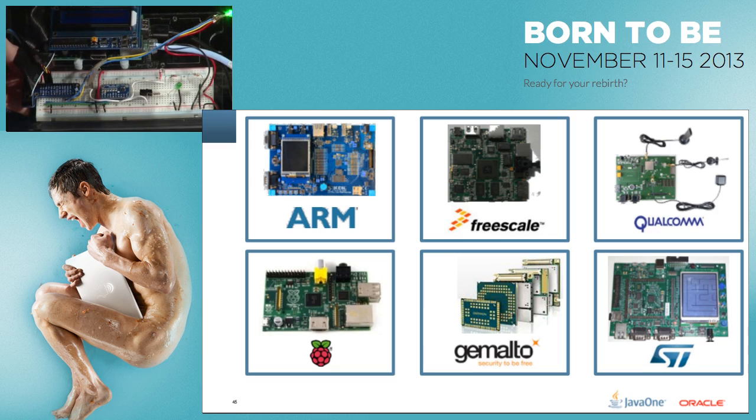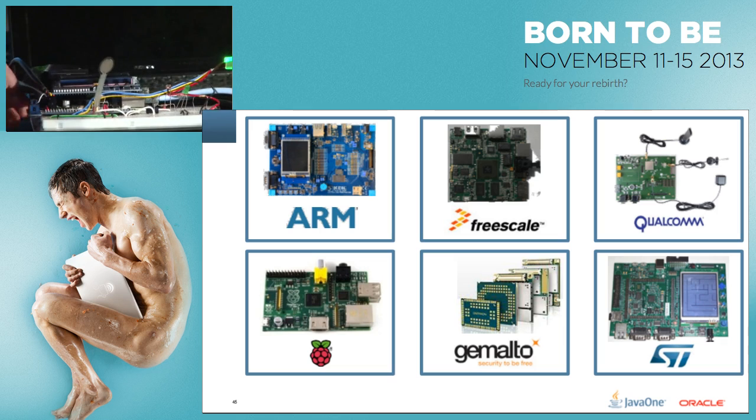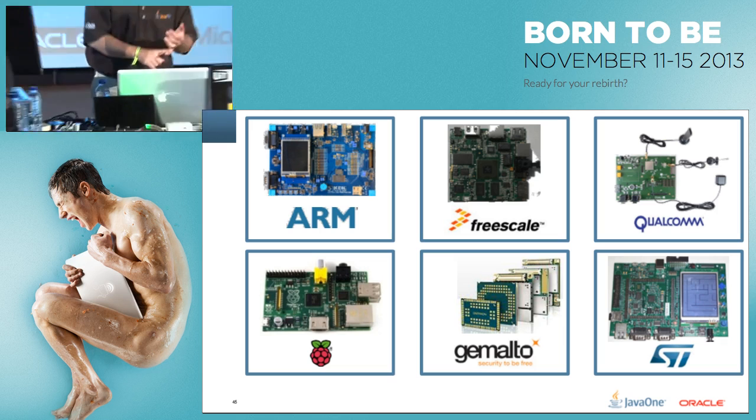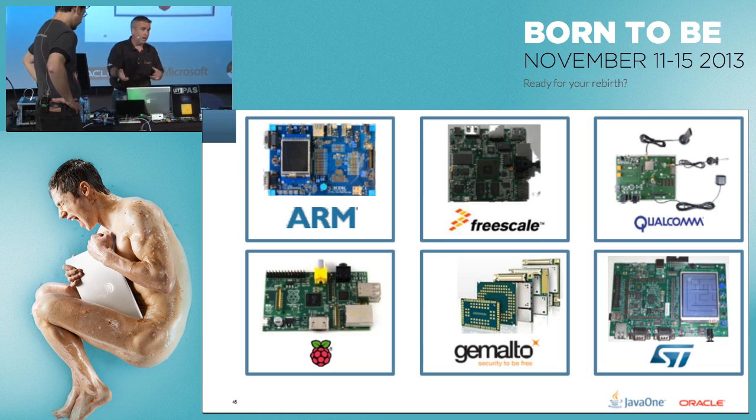Yeah, and this one's a 3-port. So you can get the 4-port one with the voltage as well. It can actually feed the voltage from your Mac if you've got a rich enough one that can push out beyond 0.7 amps. Then you can actually power the Pi and everything right from the serial tip port as well. Cool. So anyways, that's that board.